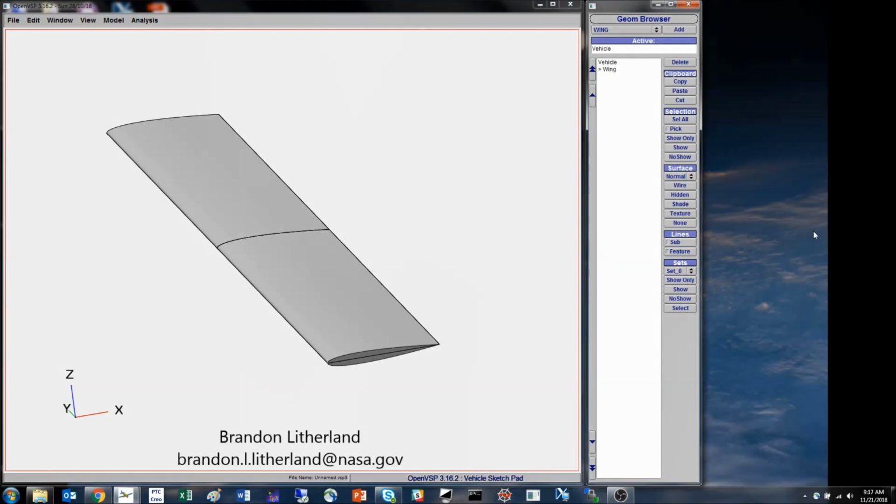My name is Brandon Litherland, and in this video we'll be going over the basics of wing design, including how to manipulate your planform sections, how to manipulate sections themselves, how to change the various parameters of your wing according to your calculated values from your project, and then how to change your airfoils, how to deal with wing placement, and then finally how to scale your model so that you can make a 3D print file at the end